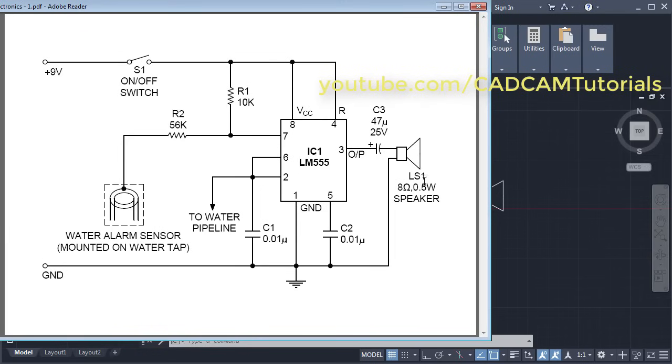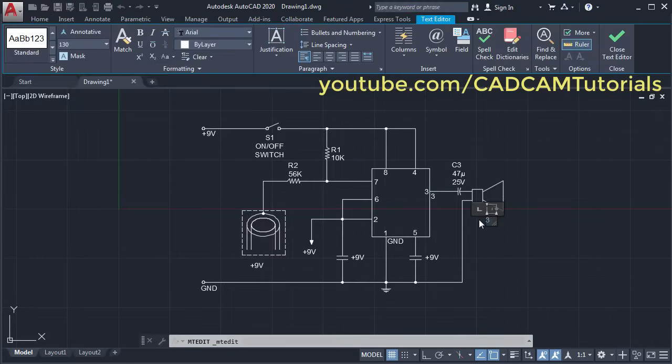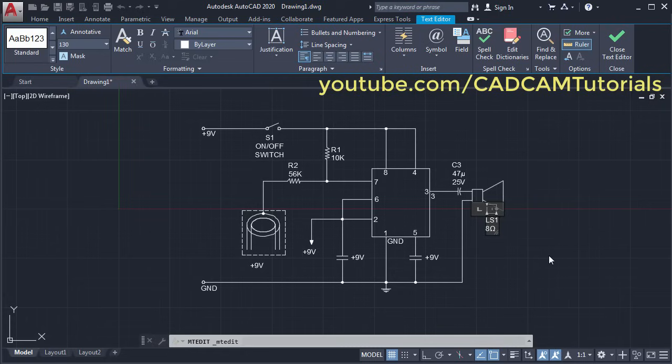Then for speaker, LS1 8 ohm 0.5 watt speaker, double click, LS1, 8 ohm. For ohm symbol, click here on symbol and click on ohm, then comma 0.5 watt, enter, speaker. Then to make it center line, select it, then click here on center, click outside.